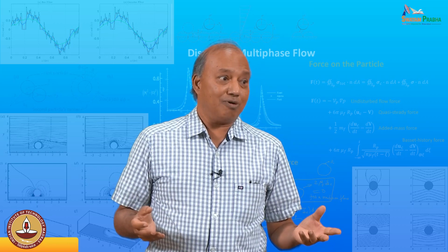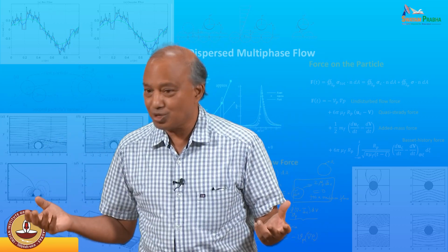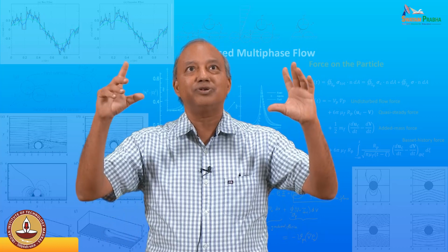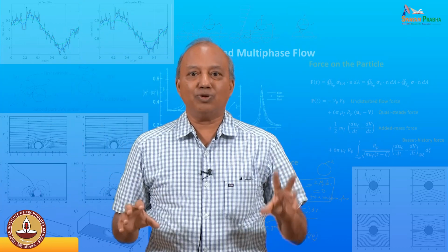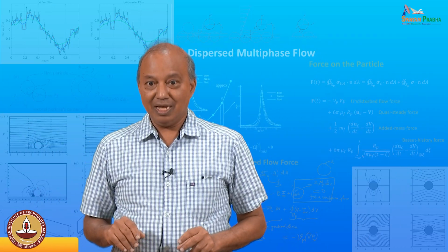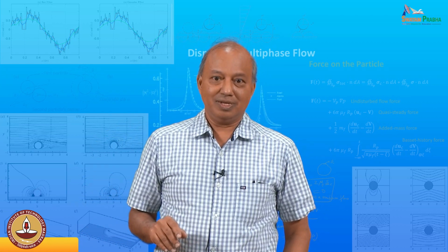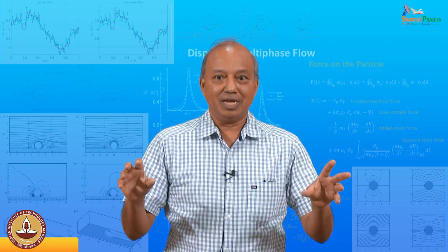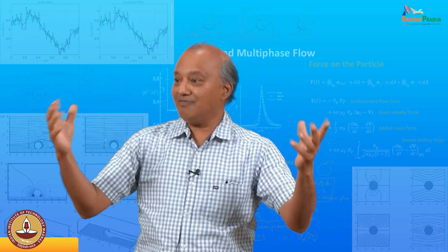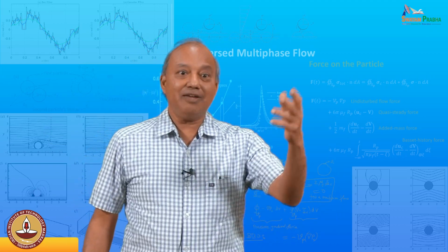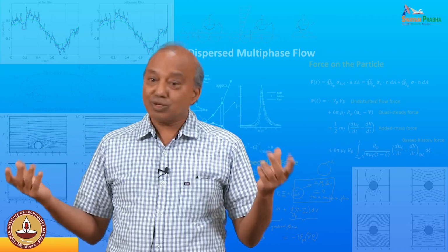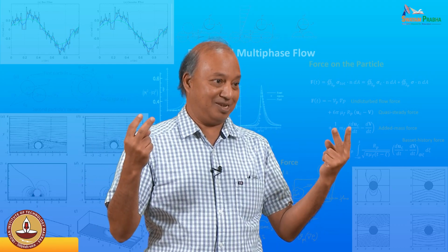In a turbulent flow, you have two sources of instability. If you remove all the particles and take pictures, turbulent eddies could be anywhere, so you have an ensemble of turbulent states. Now suppose you capture the turbulence exactly the same at two different instances. I mean, it's not possible, but say you have the same turbulence. Even then there will be variation from one instant to another because the particles are randomly distributed. So there are two sources of randomness that you want to think about.